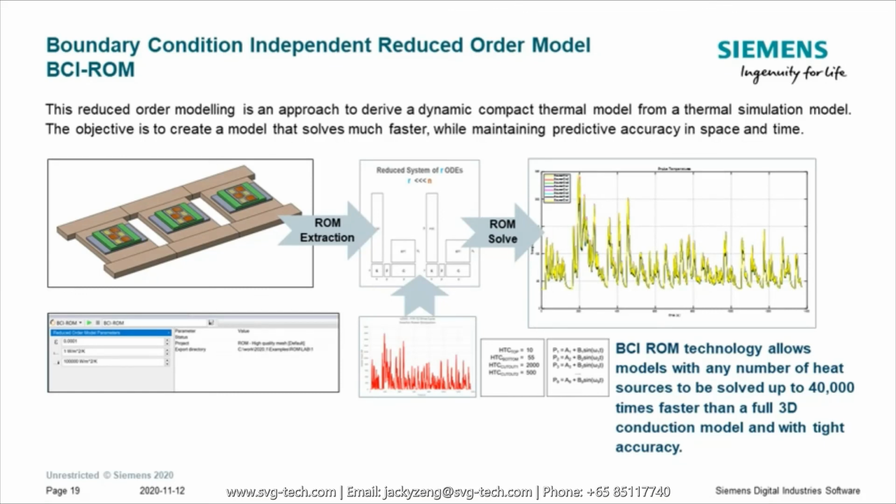And one of the more interesting recent advances is the reduced order modeling capability. So for a certain class of problems, if it meets the assumptions of this approach, you can make use of this technology. Basically, it gets down to having a linear conduction problem. Let's say you have a very transient set of inputs, like rapidly changing power inputs throughout the device. So it's conduction dominated. You can include the convection effects through heat transfer coefficients, but you're not going to model the fluid space.